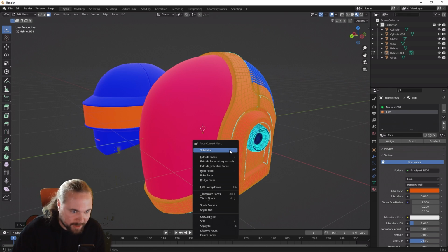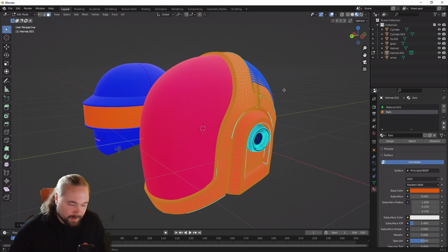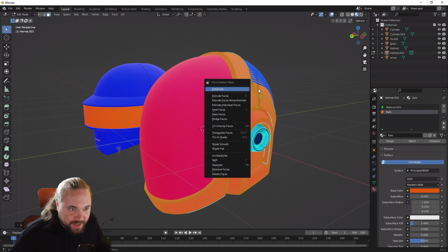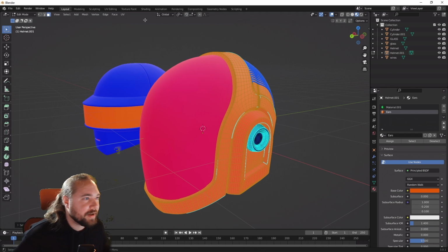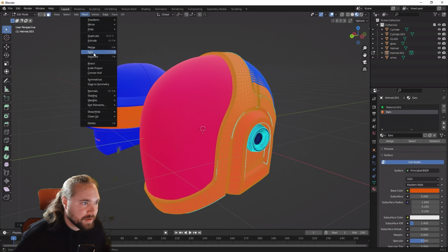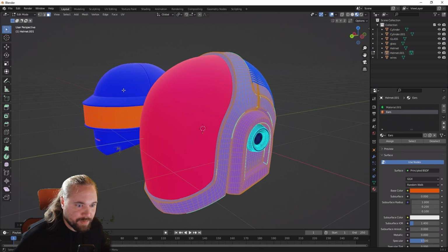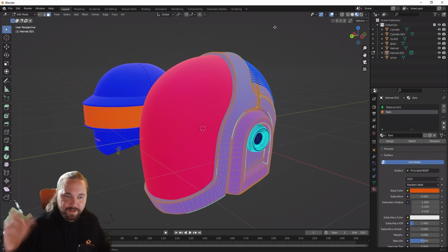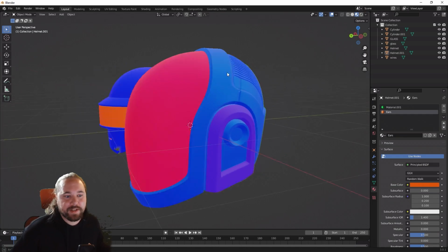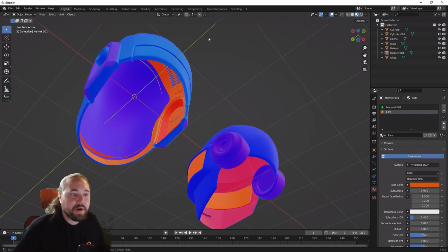So now I right click, and it's been a while since I did this. I apologize if there is a delay. I want to, is it mesh? I want normals, flip. One more time, so you see it: mesh, normals, flip. It's going to flip the normals of each surface. It's going to essentially mirror every surface.